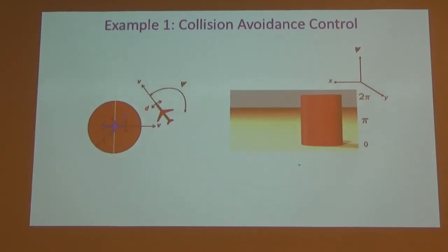Then we cast this zero-sum differential game as I described in the previous few slides, and then solve the reachable set using the level set toolbox, which Sylvia will talk about probably in 10 minutes. And here is what the reachable set computation looks like over time. This final set that I'm showing here is the converse set, so it's the infinite horizon reachable set.